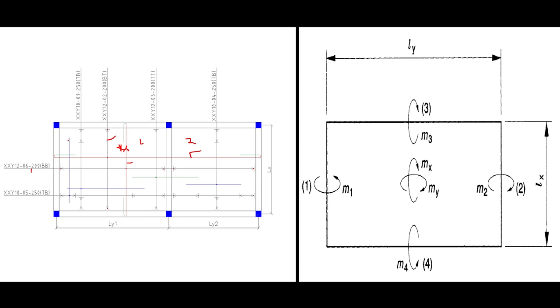Then you now ask me, what are the reinforcements in blue colors? Since I've explained to you the reinforcement in red colors and the one in green colors. The ones in blue colors are the distribution reinforcement. The position of the distribution reinforcement is the T2, which is also known as near top reinforcement. These are the reinforcements that we use to distribute the top reinforcement. If you look at the span, you can see that MY and MX are both along the short span.